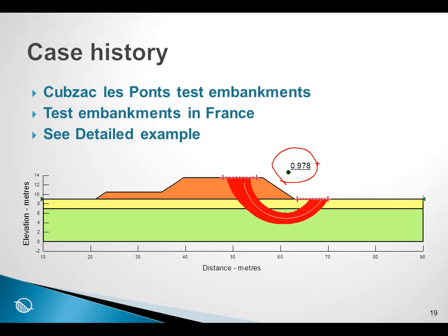Then a second, lower embankment was constructed, and it was left there for a period of 5 years with a tremendous amount of instrumentation to monitor pore pressures and settlements over a long period of time. So to those of you who are interested in this type of analysis, I refer you to these case histories in our detailed examples that we ship with the product.